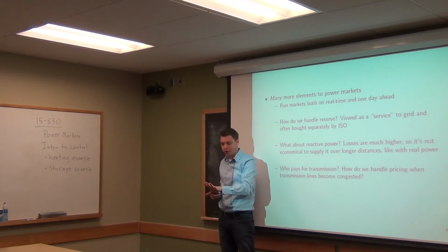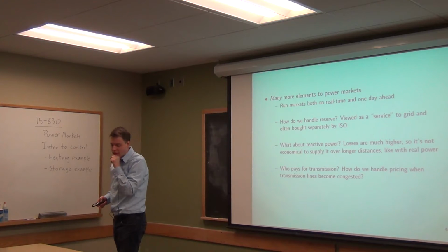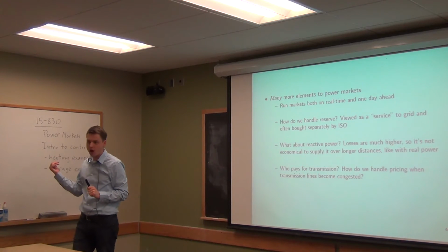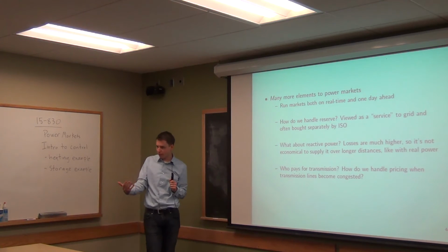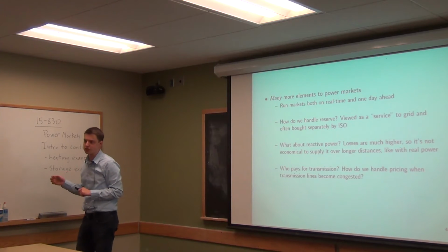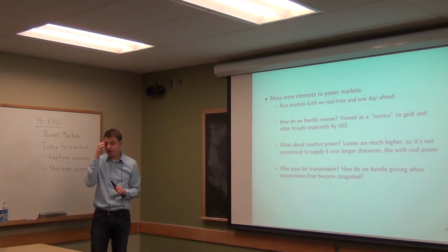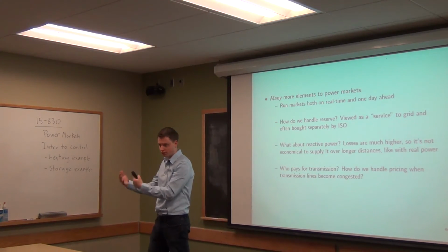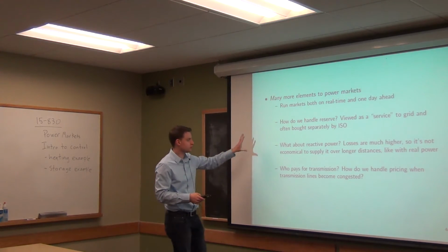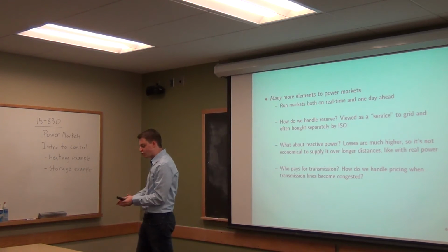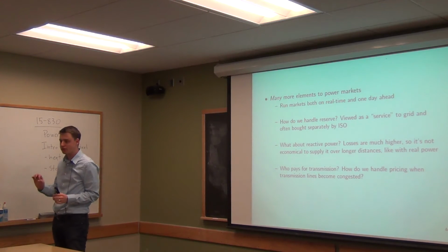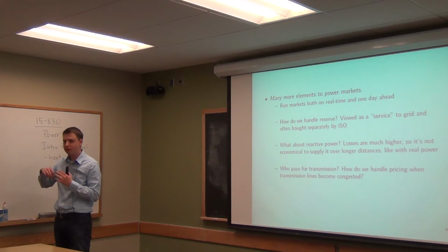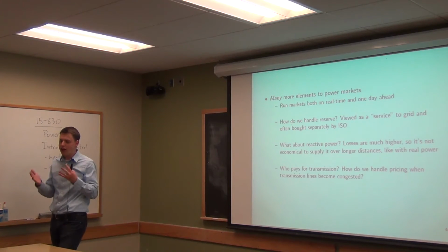The market handles a certain portion of providing energy. Again, I use the example of wanting to turn on a light switch and know that it's going to come on. But the power market, even though we solve it pretty frequently, every 5 minutes or so, is still not fast enough to account for someone turning on a light switch. So on top of this, there are a number of what are called regulation services or ancillary services that provide fast-acting support to the grid. Actually, this is not quite the same thing as reserve, so let me mention that. There is the need to track in very exact amounts, making sure that current generation exactly equals current consumption, even though that can fluctuate randomly from second to second. And so there's another set of services that are not viewed in a market way. They basically are just paid for.